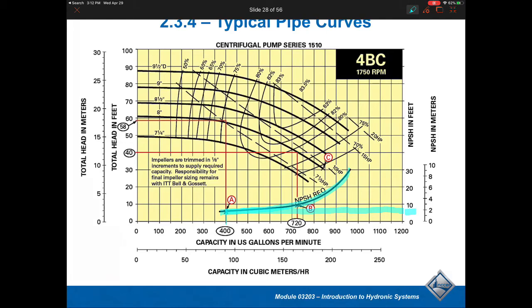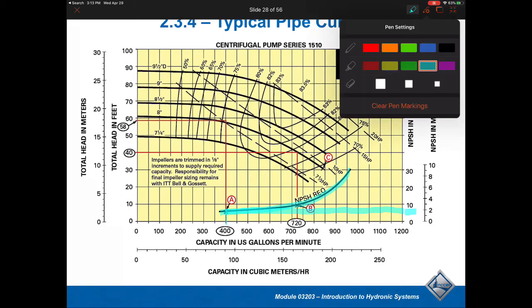That's something they talk about a little bit more in your book. Specifically, what we're worried about is when pumps cavitate, the fluid going into the inlet of the pump actually vaporizes, and usually this happens at the inlet side of a pump. It can also happen if you have valves that throttle flow. There's a number of things that can do that. You have to be really careful with that. That's one I would point out, and there are a couple other things that we'll also deal with.